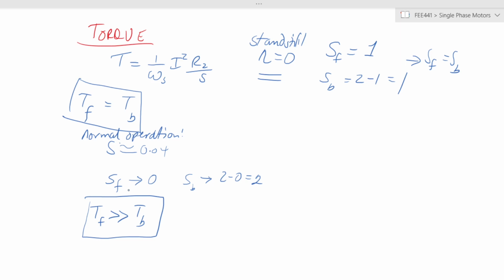And this characteristic shows that if we are able to give the induction motor a push in any direction, it will start. But if it is at complete standstill with no force acting on it from the outside, it will not be able to start itself, and it will remain in that position even though you have applied a voltage to it.